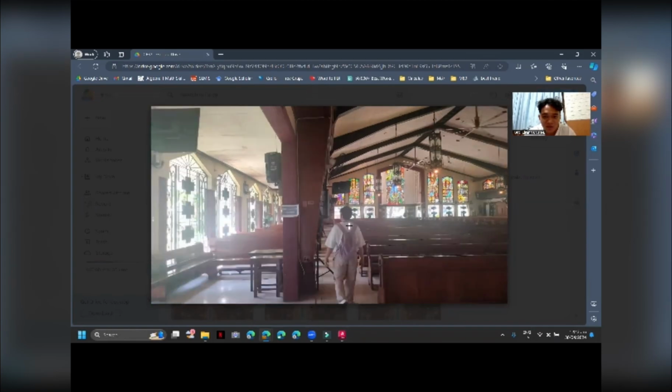We measure it on the screen or anywhere. Then we have a proportion, the known height over the measured height on the picture. Then we equate it to another ratio of the building. So we have the unknown value, which is the real height, and then we have the measured height on the picture. Then we can get an approximate measure of the element that we want.